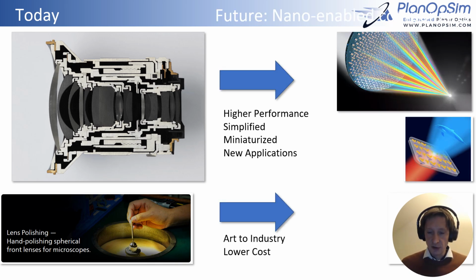Metasurfaces promise to enhance this performance and make it much lighter, much smaller, and much simplified, and even lead to new applications by using nanostructures that locally control the behavior of the light, then distributing these over a large wafer so that we end up at a performant optical component. And all of these metasurfaces can be created using standard lithographical techniques known from the semiconductor industry.